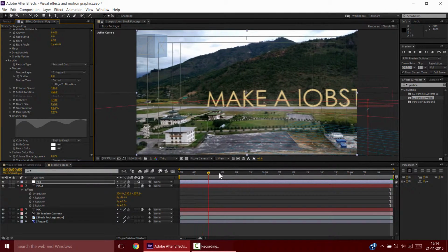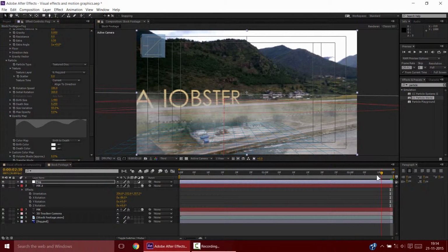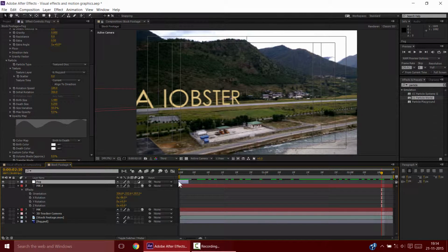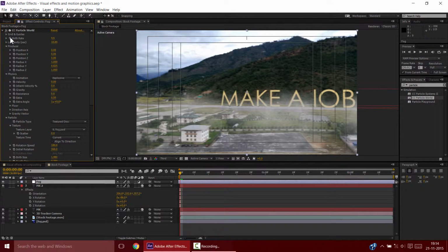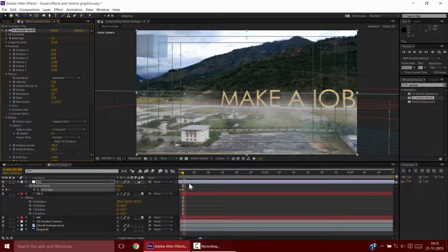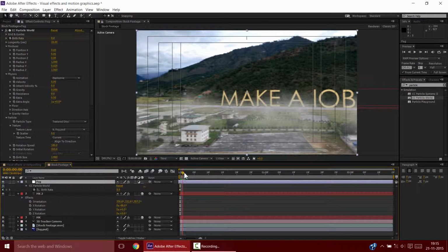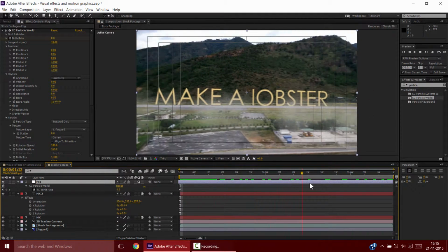So now if we take a look, starting from the footage, the particles start to appear, but we don't want this look. We want particles to stay where they're born. So I'll shift this footage, put it from the start, and I'll extend this till the end. And what I'll do is keyframe the birth rate, press U, and press page down for the next keyframe, and I'll turn down the birth rate to 0. So now if we shift back one frame, we see the particles won't change from here. And it's kind of close to what we want it to be.